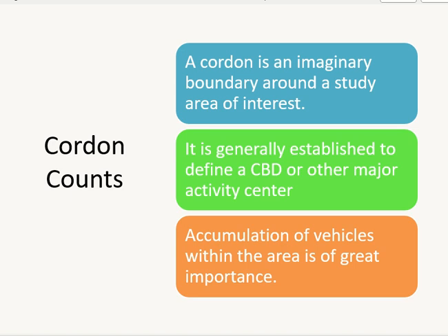City Center, yes. Okay, so you make your boundary around that. But obviously, it's easier to manage a boundary around only the city center, easier to collect data, but that is not the only thing which is attracting traffic in that area, right? So you are not covering all the traffic generators, all the traffic attractors. So this is when you go too small.